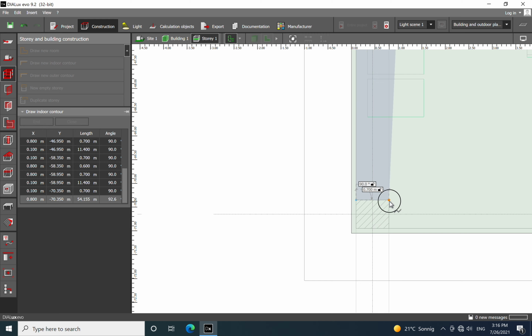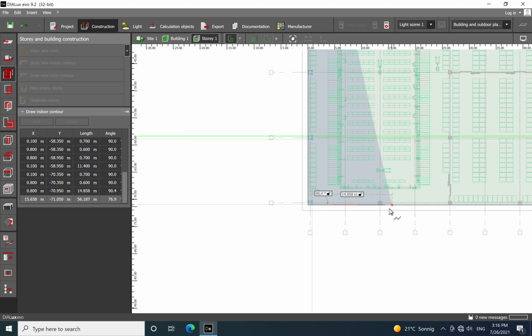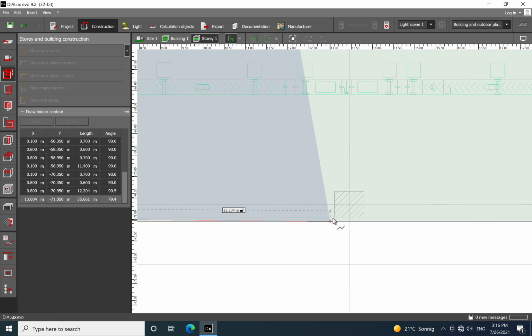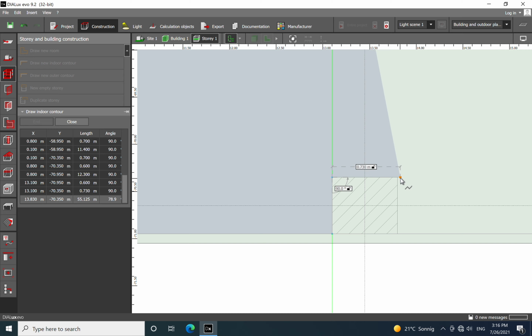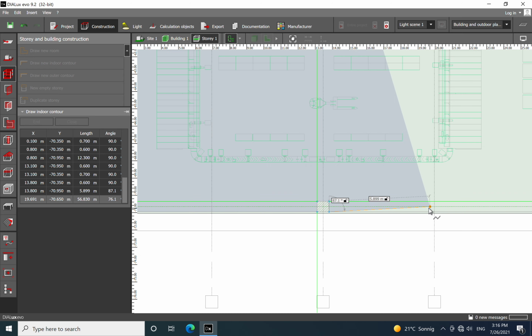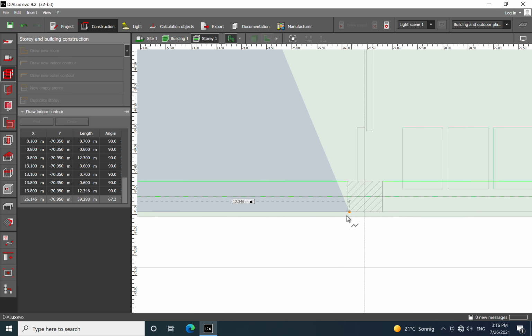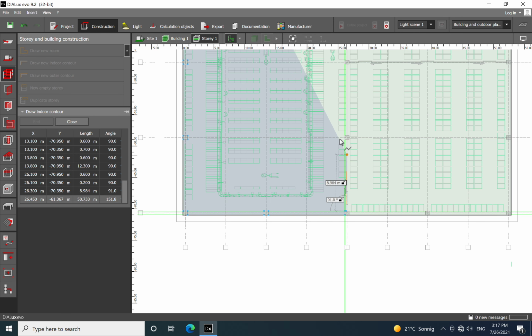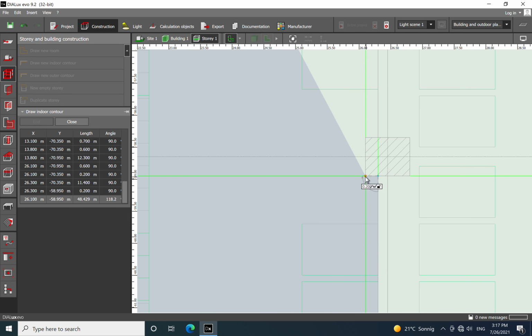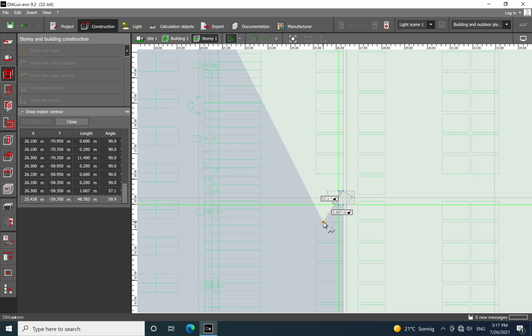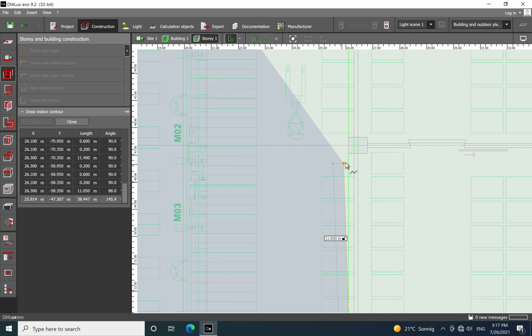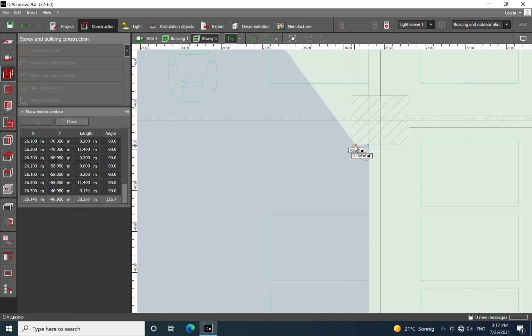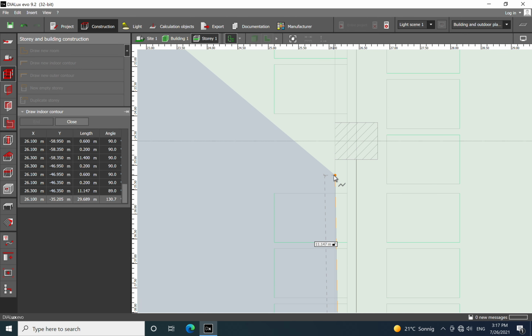For the production line, what I want to mention as very important is the requirements for the light level that we need to fulfill. For example, if you have production of fine parts or medical things, you need to have from 500 lux to maximum 1000 lux, depending on the space designated for that production line.